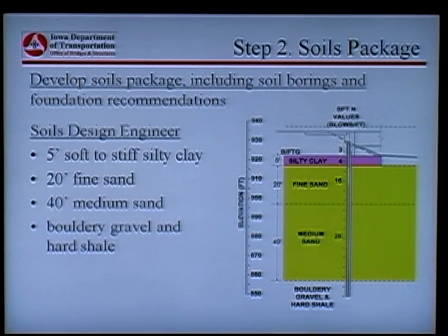Step two is to come up with a soil package. It's basically to determine the site investigation and recommend a foundation system for the bridge. So this is a soil profile. As you can see, you have 5 feet of soft to stiff silty clay, 20 feet of fine sand, 40 feet of medium sand, and below is bouldery gravel and hard shale. It is primarily a non-cohesive soil profile, but we will check and verify that.